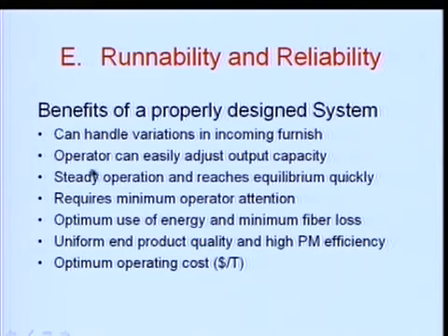Operators should be able to easily adjust output capacity depending on the paper machine. Steady operation, and reaches steady state or equilibrium quickly. Requires minimum operator attention. That's where the system controls again come into the picture. If the operator requires constant attention, then either the system is not going to get the attention from the operator, or your system is in an upset condition most of the time.